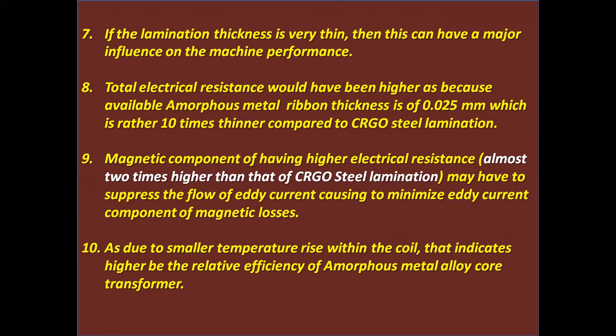Number 9, the magnetic component having higher electrical resistance, almost 2 times higher than that of CRGO steel lamination, has to suppress the flow of eddy current, causing a minimized eddy current component of magnetic losses.